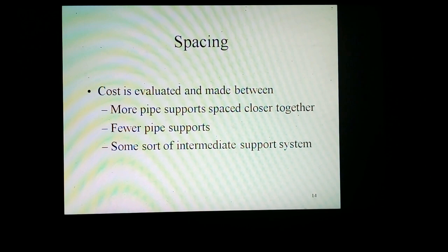The concrete fireproofing can be cast in place onto or around the steel columns and beams, or it can be precast onto the columns and beams prior to installation. The reinforced concrete pipe supports can also be cast in place or precast, then field erected. The space requirement for a reinforced concrete column or beam is about twice that of bare steel.